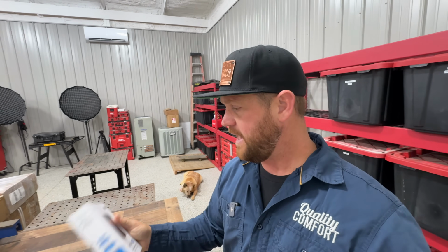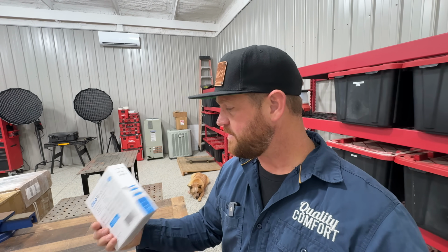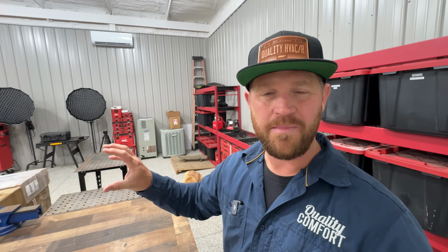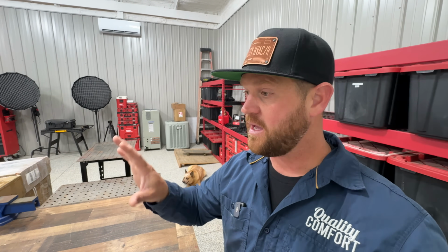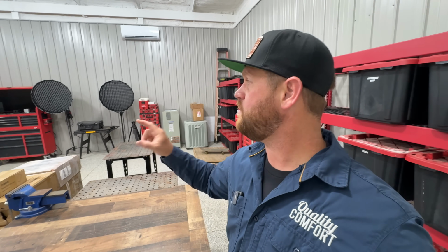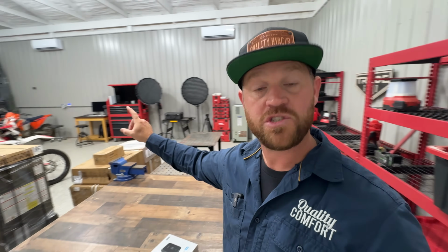That's pretty cool. Now you can have it set up to where it's kind of like a desk mount. You would just sit it on a table. It comes with a cradle, and you plug it with USB-C into your outlet, right? That powers it up, and then it controls the systems that way. Or if you want more of a seamless, wall mount look, it comes with a back plate, and then you just need to get a transformer down to 24 volts, and then you can wire it up with 24 volts and use it like a normal traditional thermostat mounted on the wall, which is pretty cool. And I think I'm going to do that here because I have all my conduit run external or flush mount on the outside of the wall.